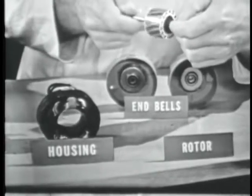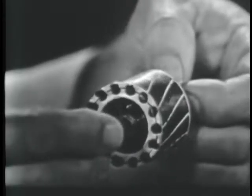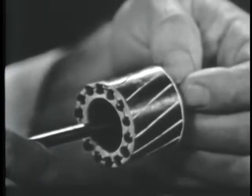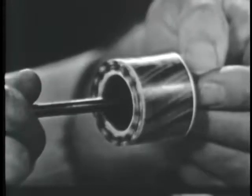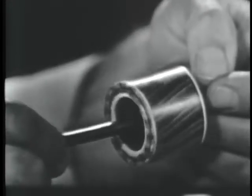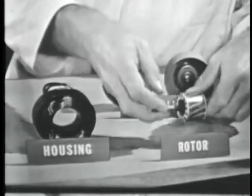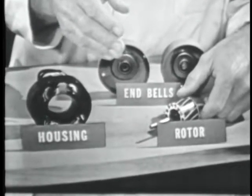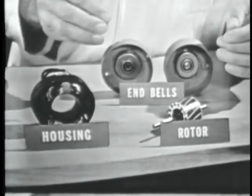All right, the rotor has no commutator, no slip rings, and no wire windings. It doesn't look at all like the rotor used in DC motors, does it? Not at all. Now, this particular rotor design is called the squirrel cage rotor because it resembles the exercise cages used for pet squirrels. And like the squirrel cage, the rotor is very simple to construct. Simplicity of construction, which of course leads to lower cost of manufacture, and a very rugged design, makes the induction motor a very popular one.